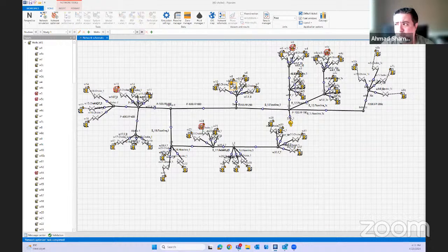That's why it's very important that you start discovering and exploring these solids early enough and try to treat them by scraping, by injecting special inhibitors early enough, so that the problem doesn't appear more. Okay.